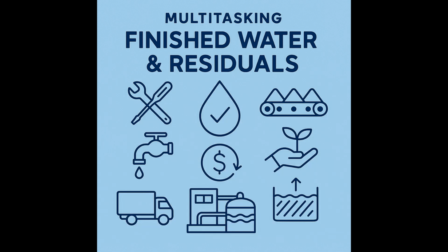Wow, okay. So after filtration, the water's pretty clean. Getting there. Now it's into the clear water stage. Disinfection happens here, usually with chlorine. Then the water sits in tanks for contact time and storage. Then it's pumped out via the finished water pumps into the distribution system, the pipes leading to homes and businesses.